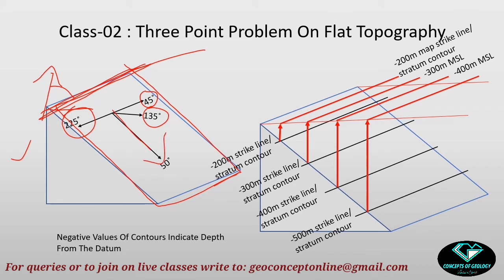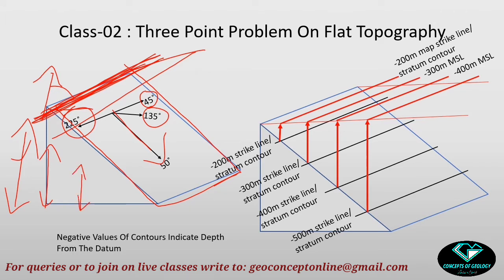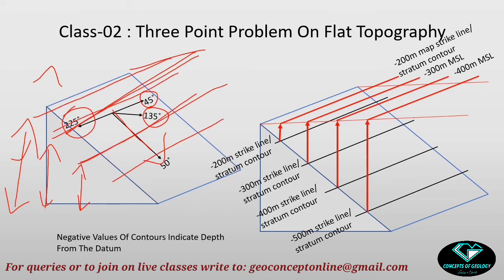degrees here. Okay, now if this is the strike line, I mean at this level, at this height, I have a horizontal plane which is intersecting through this line. Now suppose at this height I also may have a horizontal plane which will intersect the inclined plane here, and again at this height I may have a horizontal plane which will intersect the inclined plane here. I may have a group of parallel lines, all will be strike lines of the inclined bed, but the level will be different. Exactly the same thing is done in the case of this figure.